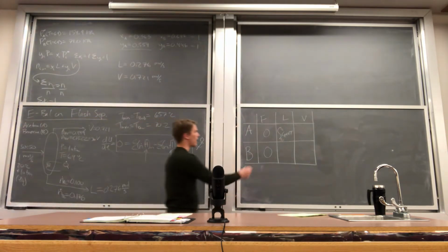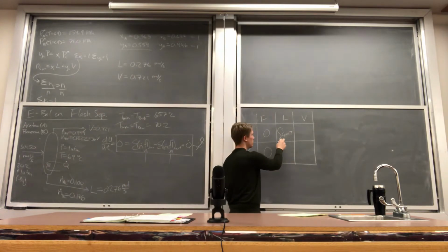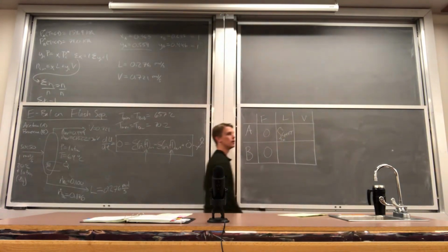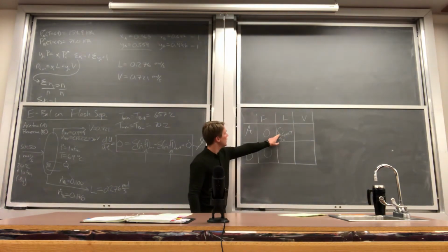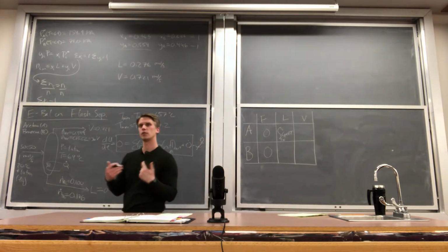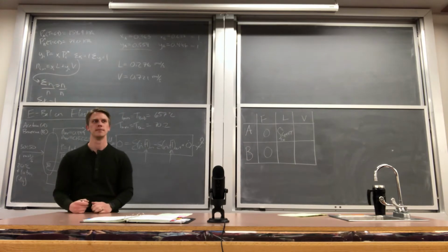Right, we are going from our reference state condition, or I could say T ref if we wanted to be a bit more general. And the same thing would be done here. So the only difference between the enthalpy of the liquid for acetone and the enthalpy of the liquid for benzene is that they have different heat capacities, because we've started off at the same reference state.